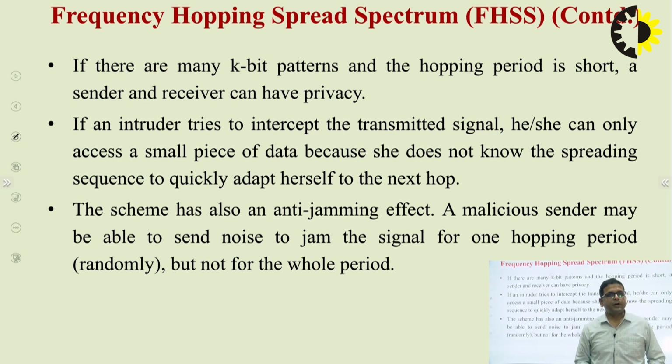If the benefit of frequency hop spread spectrum is that, suppose the intruder traces our carrier frequency, and after knowing the carrier frequency, he tries to send the same frequency from his end, when the signal sent by the enemy reaches, in frequency hop spread spectrum the desired frequency has already changed from the previous one.